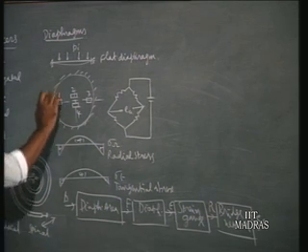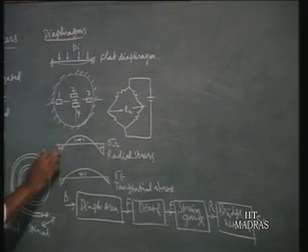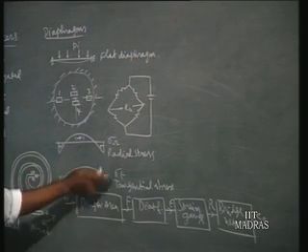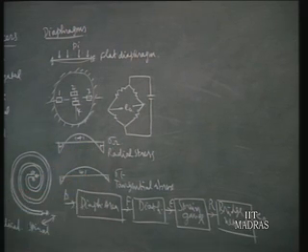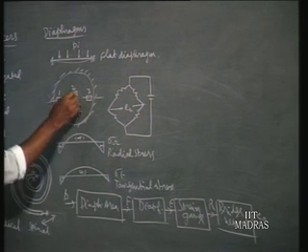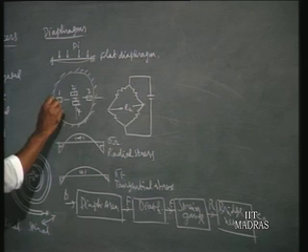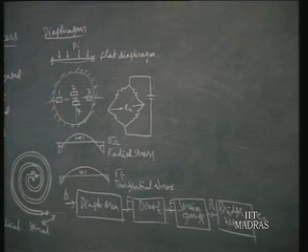If we look near the fixed end of the diaphragm, we have compressive stress or strain, in both radial as well as tangential directions. Near about the middle of the diaphragm, we have the tensile strain. So accordingly, fix the strain gauges. 1 and 3 will pick up the compressive strains; 2 and 4 will pick up the tensile strain.